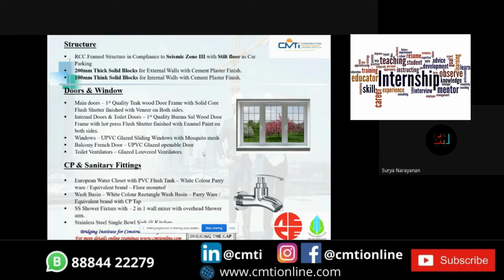For doors and windows, a first quality teak wood door frame with solid core flush shutter finished with veneer on both sides should be provided for the main doors. A first quality Burma style wood door frame with hot press flush shutter finished with enamel paint on both sides should be provided for internal doors and toilet doors. UPVC glass sliding windows with mosquito mesh should be provided for windows, where UPVC stands for unplasticized polyvinyl chloride, and it is also used as an openable door for the balcony French door. This image shows the French door representation. Glazed louvered ventilators are used for toilet ventilators.